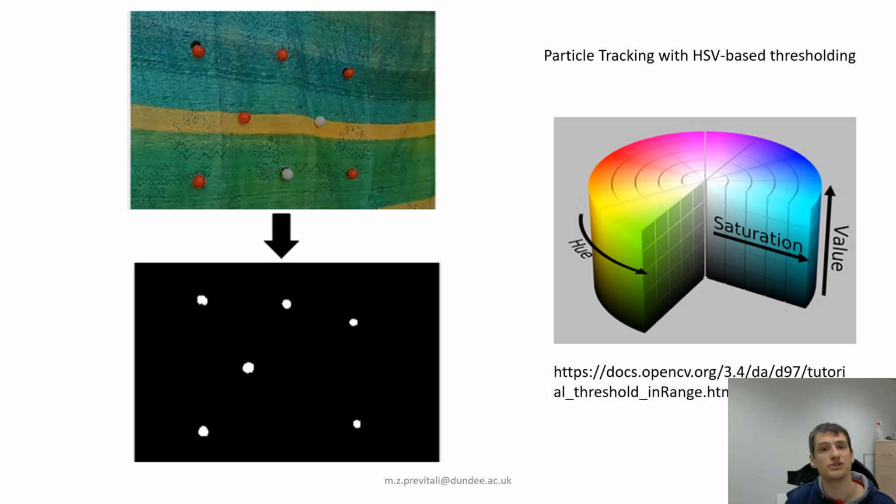The main advantage of using color targets, which we separated from the background using HSV-based thresholding, is that instead of separating everything based on the intensity, which can change a lot in the field due to natural lighting, it's much easier to separate avoiding the colors that you can find in the field, for example red or purples, which are not typically occurring.